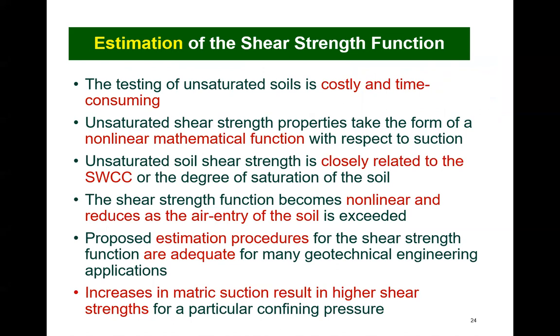The unsaturated shear strength is closely related to the soil water characteristic curve, or the degree of saturation of the soil. The shear strength function becomes nonlinear as the air entry of the soil is exceeded. The proposed estimation procedures for the shear strength function are adequate for most geotechnical engineering applications.